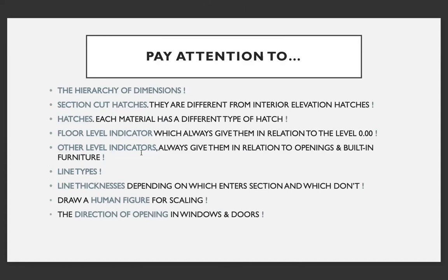Other level indicators, always give them in relationship to openings and building furniture, line types, line thickness, and if necessary, draw a human figure for scaling, for people to understand the human and object relationship, or human and space relationship, and the direction of opening in windows and doors.